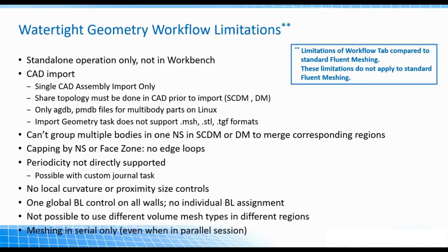So here are some limitations on the workflow. The first one is that it's available only in the standalone version of Fluent. If you go in through Workbench and try to open Fluent in meshing mode through Workbench, that workflow tab just won't be there. You'll only have access to the tree-based meshing. So it's something to keep in mind whenever you go through to Fluent in the standalone version. From there, of course, you can save your mesh and export it to somewhere else if you'd like, or go directly into Fluent solution mode. But you do have to open it in the standalone version.